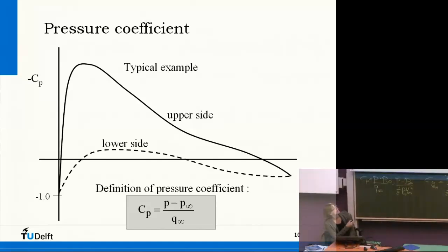Because now the top of the airfoil, so Cp on top, is here. And so we have top and bottom Cp. You can easily see that the pressures on the top minus the pressures on the bottom give something like lift. So the area between them is the lift, with the top on top and the bottom on bottom. That's why we plot minus Cp. But the Cp at the stagnation point is 1, and it is the maximum, so all Cps larger than that one should be here. It is the maximum Cp, but in the minus plot, of course, not.